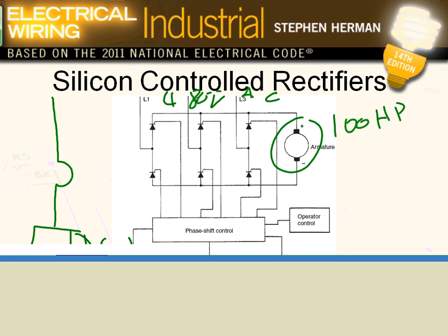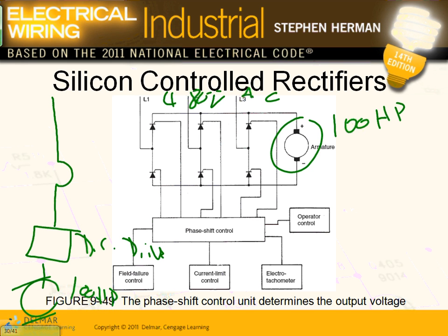And this is my, I don't know, 100 horsepower. Let's say that's 300 amp. And this is my 480 system. See what you do? Here's your DC motor, tied to a DC drive and connected to an AC system. Can I get you guys to understand how you tie a DC motor to an AC system through a DC drive? Can I have a thumbs up, Chad? That's very important to understand that. You get a DC motor tied to an AC system via a drive. That's what you're looking at right now.